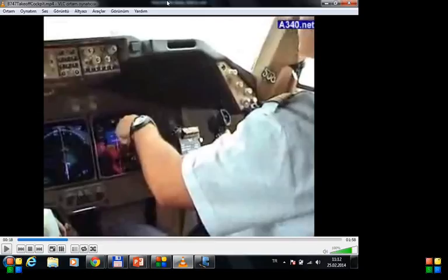So the pilot control that's supposed to make the aircraft roll towards the right had the opposite effect, because the left and right ailerons were misconnected, and because of that the airplane crashed, and I think 3 or 4 people died as a result of that. To be able to prevent such accidents, it's a very simple test, but the pilots have to actually make this test.